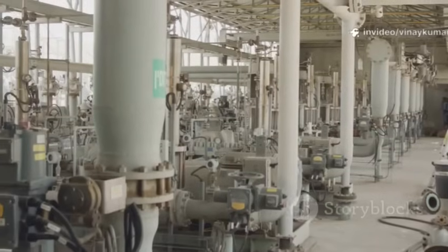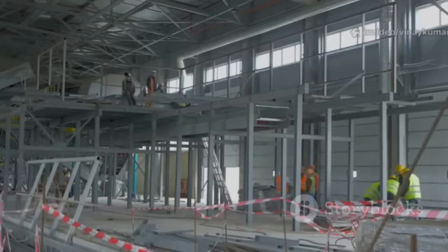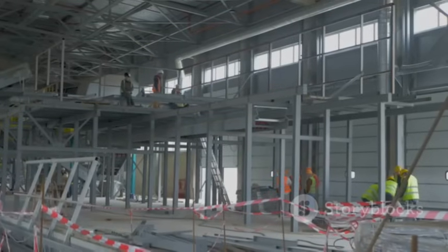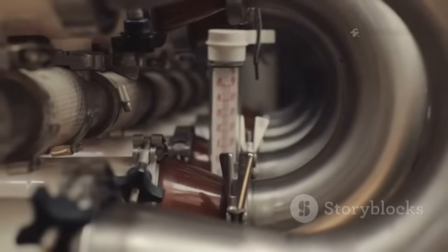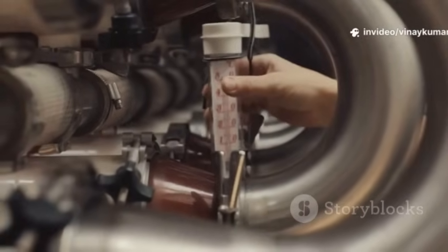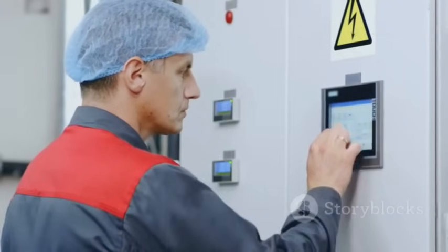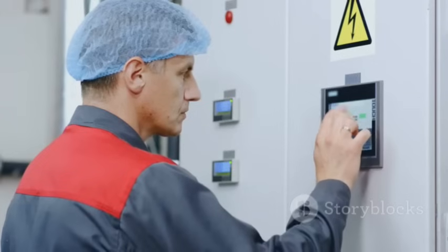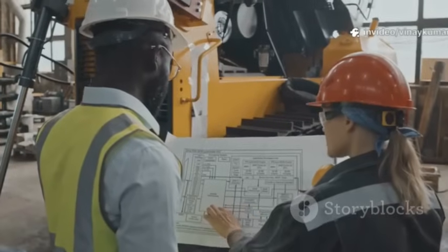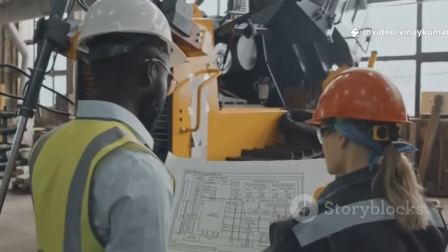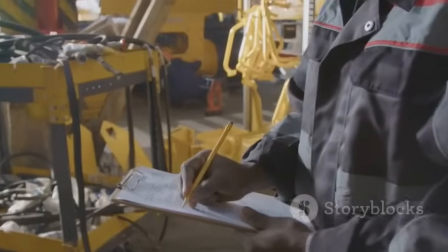The MOC procedure applies to changes in process chemicals, technology, equipment, and procedures. It even covers changes to facilities that affect a covered process. The only exception is for replacement in kind, for example, replacing a broken valve with an identical new one. Anything else, from using a different supplier for a chemical to changing the alarm set point on a temperature controller, must go through the MOC process. It's designed to catch the ripple effect, those downstream impacts that might not be immediately obvious to the person proposing the change. The written MOC procedure has to address several key things.